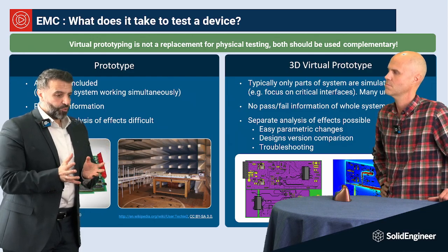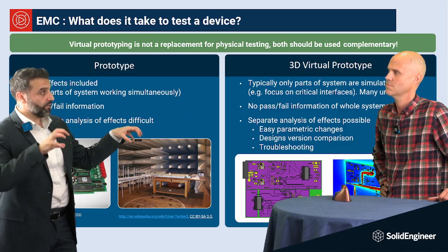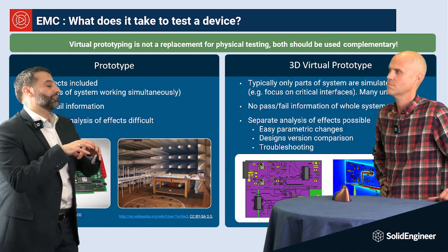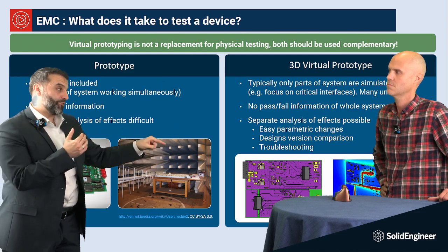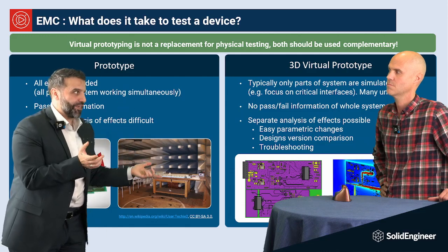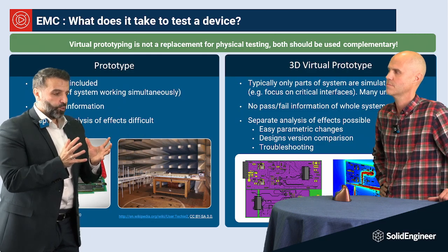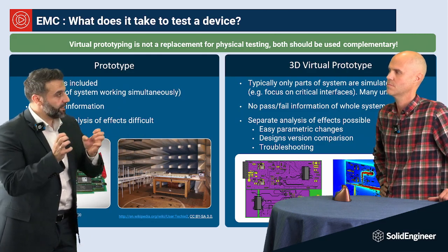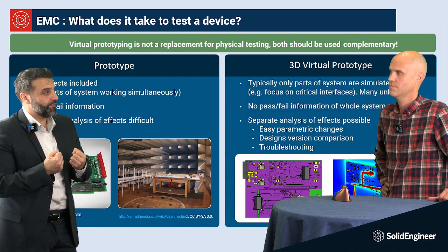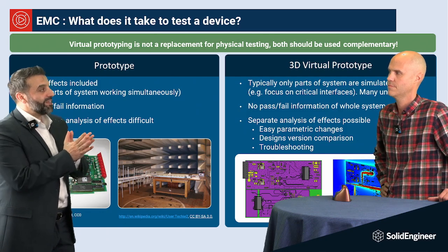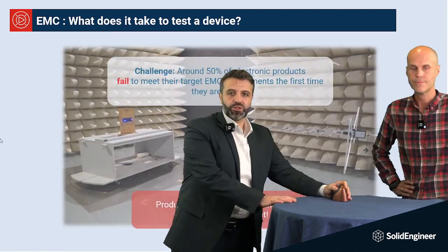Now imagine when the PCB gets denser. It means that the info sent from point A to point B will be quickly deformed. Usually we send a square signal, and you don't want this square signal to arrive in a triangular shape, because it's zeros and ones going over there. And usually we need to make sure that the signal is well received by the destination, right? For example, if the memory is receiving info from the CPU, we need to make sure that the memory is receiving the good signal. And for this, eventually, we have a study we call the eye diagram.